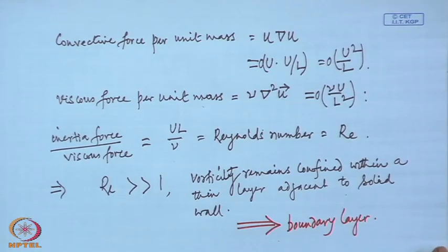So, for a high Reynolds number flow, a boundary layer develops over certain geometries, and within this boundary layer the velocity changes smoothly from 0 on the surface to the inviscid flow velocity at the edge of the boundary layer, and within this layer the vorticity is non-zero, the flow is rotational.